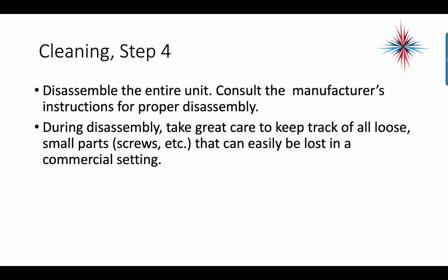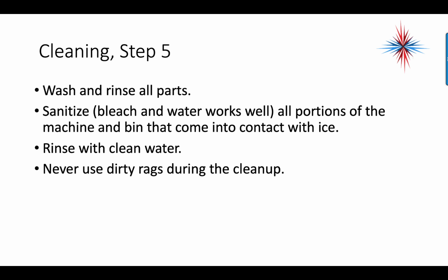Disassemble the entire unit. Consult the manufacturer's instructions for proper disassembly. During disassembly, take great care to keep track of all loose small parts such as screws, little bolts, little plastic pieces that can be easily lost in a commercial setting. Remember, around ice machines, a lot of times there's a floor drain. I can promise you that the little piece you drop by accident will go down that floor drain.